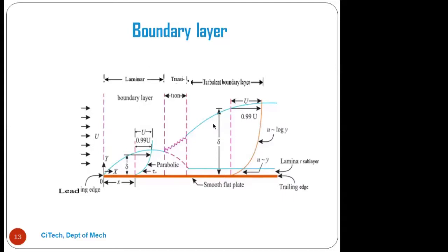If the Reynolds number is more than 4000, the flow is called turbulent. If the Reynolds number is greater than 2300 and less than 4000, that is called the transition period, from laminar to turbulent when the fluid flows over the plate. Understand? So this is the importance of the Reynolds number.